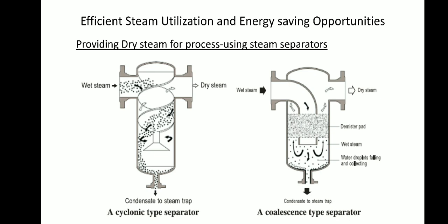The steam separator may be installed on the steam main as well as on the branch lines to reduce wetness in the steam and improve the quality of steam going to the units. Changing the direction of steam flow in the separator causes the entrained water particles to be separated out and delivered to a point where they can be drained away as condensate through a conventional steam trap.